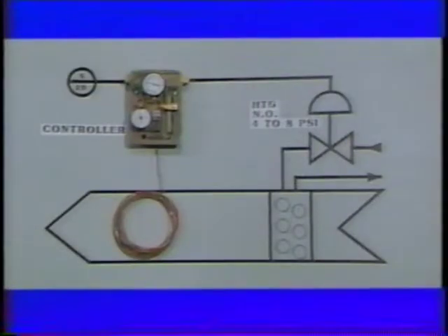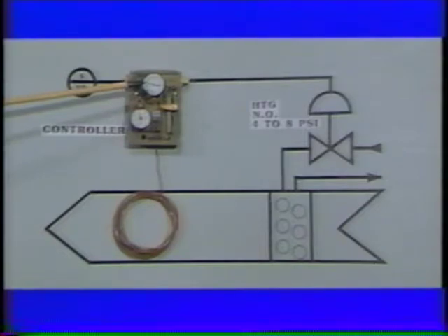In order to demonstrate the third key benefit of pneumatic transmission systems, let's add one more requirement to our original application. We started out requiring control of discharge temperature. Now we want both control and indication of discharge temperature. Going back to the conventional system, where can we install a gauge that will provide indication of the temperature measured at the element? Well, there's only one variable pressure in this system, and that is the controller output. Can the controller output be used to indicate temperature?